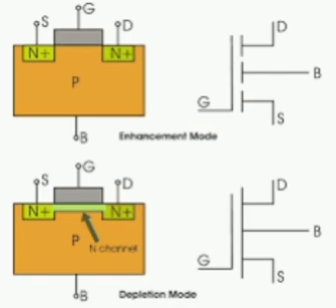FET is a symmetrical device where drain and source can be interchanged, while BJT is not a symmetrical device. JFET channel is wedge-shaped. The process of varying channel width by variation of VDS is called channel width modulation. In N-channel JFET, channel width is narrower near the drain.